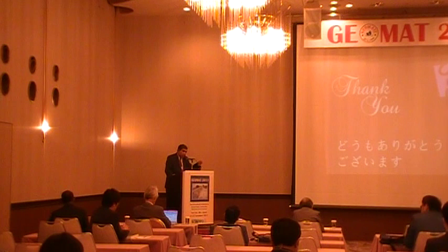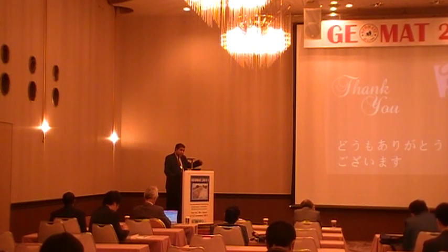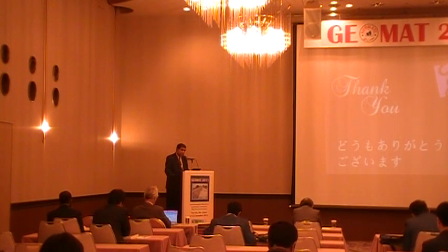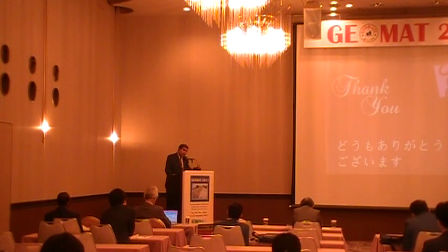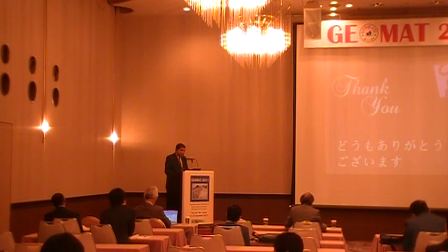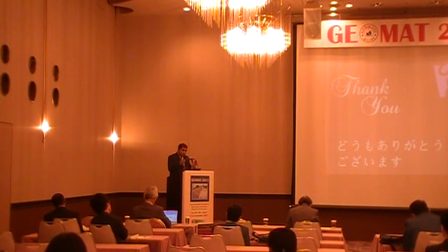We even used a pocket penetrometer in the field whenever we are collecting the samples, to insert it and back calculate suction values. We can also use what is called the filter paper method, which can also be used for measuring the suction. Another way is if you can measure the soil water characteristic curve, and when you are sampling, you get the water content, and from the soil water characteristic curve, you can have the suction. But there is the effect of hysteresis.